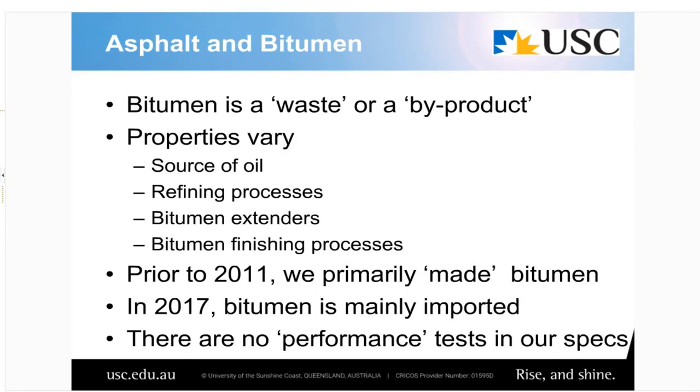If you have an aggregate source that has only a very small portion of fine material in, you can add some lime to essentially correct the grading. Typically, we'd be looking for about 5 to 6% of the overall aggregate being smaller than 0.075 millimetres in diameter, so very small material, and lime will supplement that if you have a particular aggregate source that's deficient.